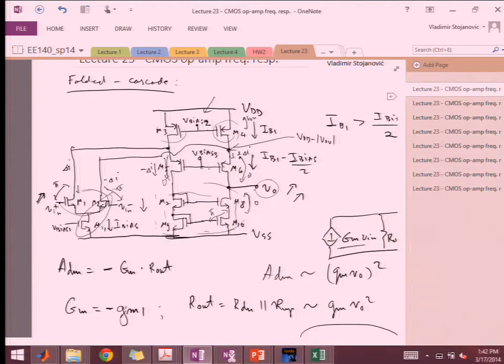Okay, yeah, great. So the idea is with all the current sources and current mirrors, we do sort of the KVL around VGS voltages, right? So you go from VSS up this VGS, because they're connected. Then you have a bridge to this VGS. So now you know at this gate, you're 2 VTH plus 2 VOV. And then you have to come down by VTH. Right? So that's still keeping M8 in saturation.